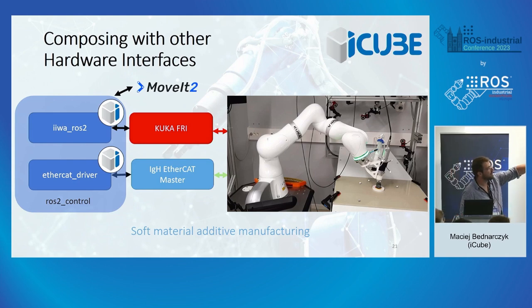Here you can see we also have a tracking unit, an optic tracking unit. We also developed drivers for it to integrate it into ROS control, and basically we can then put all the sensors, actuators, robotic system, EtherCAT buses together into one single component based on standard hardware, which can be configured directly on the fly without the need of adding additional things. And the advantage of using it that way is, in contrast, if you would have particular nodes, all the different components are well synchronized together.